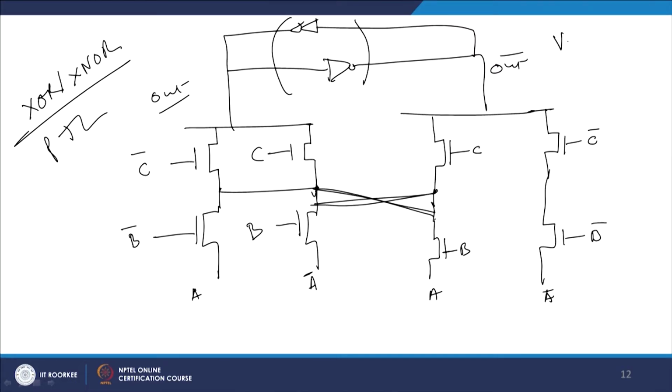that you always have a VSB, because please remember, in conventional CMOS architectures, my source was grounded or connected to the most negative terminal. This ensured that the threshold voltage change was 0. But in this case, if you see carefully, you are applying a potential at the source end. So, your VSB is not equal to 0 at any point of time, because source and bulk are now at very different voltages. As a result, the threshold voltage will change, and that is quite critical.